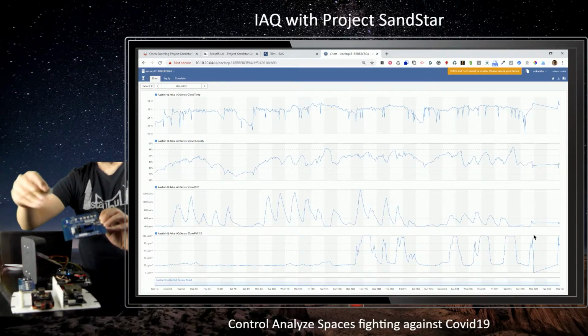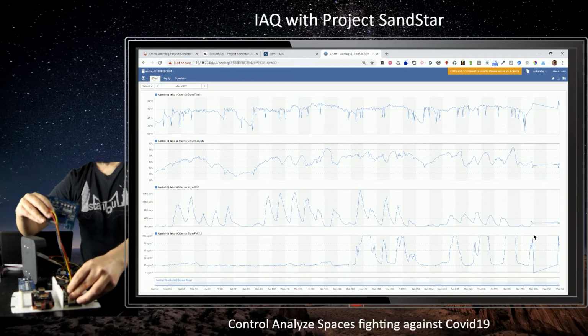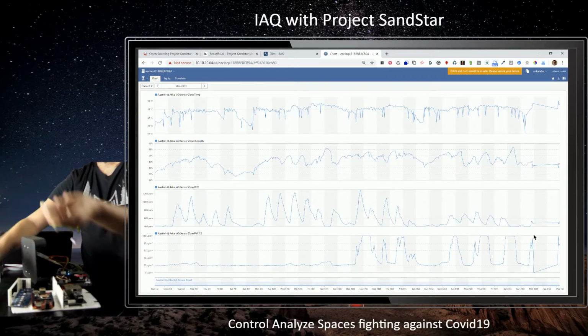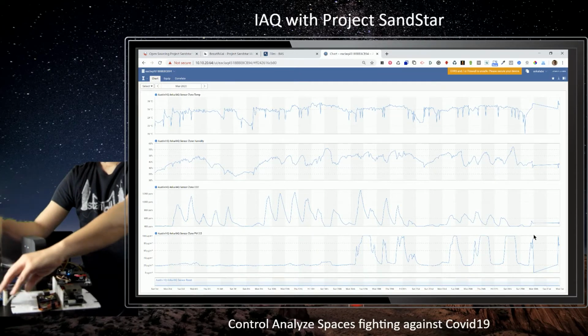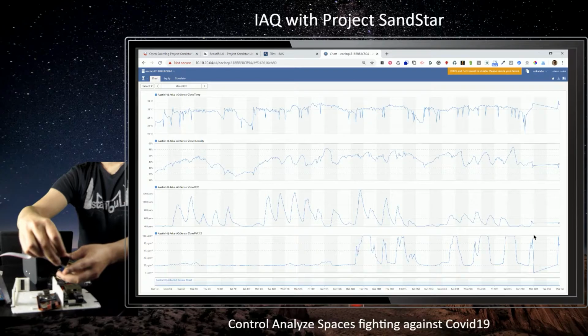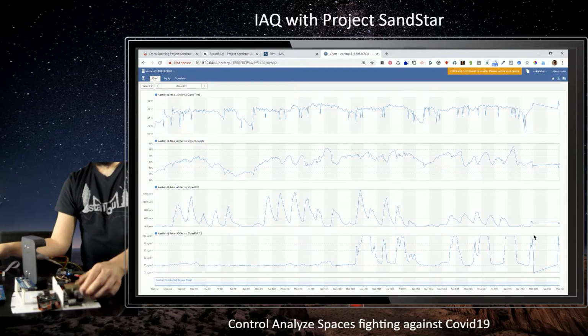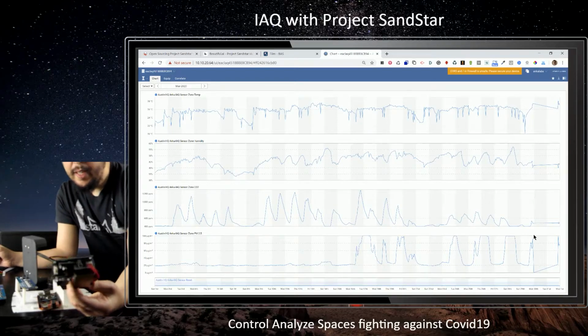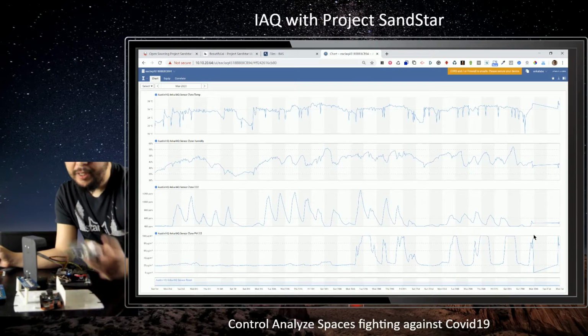The connection that goes from here to the AM4100L is something like this. It's a JST cable that you would be purchasing. Also, the cable for the LED light is basically a box model type. It's basically a ribbon cable that you will have to purchase. The sensor looks something like this. This is AM4100, and it's basically a dev board with CO2 sensor, particulate matter, temperature and humidity, and VOC all built in, and it communicates over a UART.